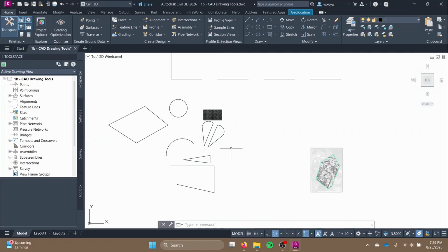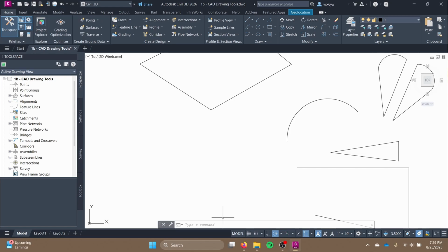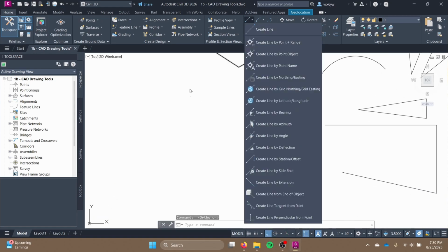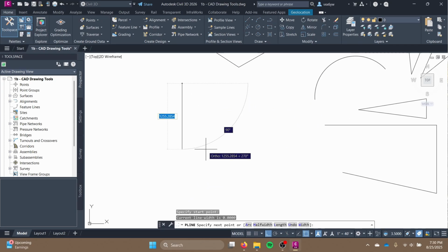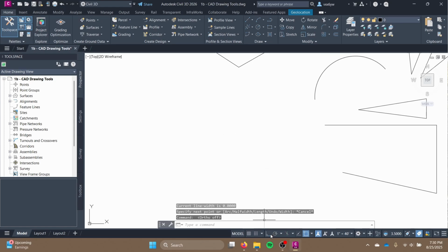All right, on the home stretch of this deliverable, just two more things to do. One thing I want to quickly mention in this tutorial is this bottom set of controls. A lot of these have to do with object snapping or grid snapping. For example, you can restrict the cursor to move orthogonally. And that just means, for example, if you create a polyline, when you make it, it only snaps to 90-degree angles. That's helpful sometimes, but in general, I'll keep it off.